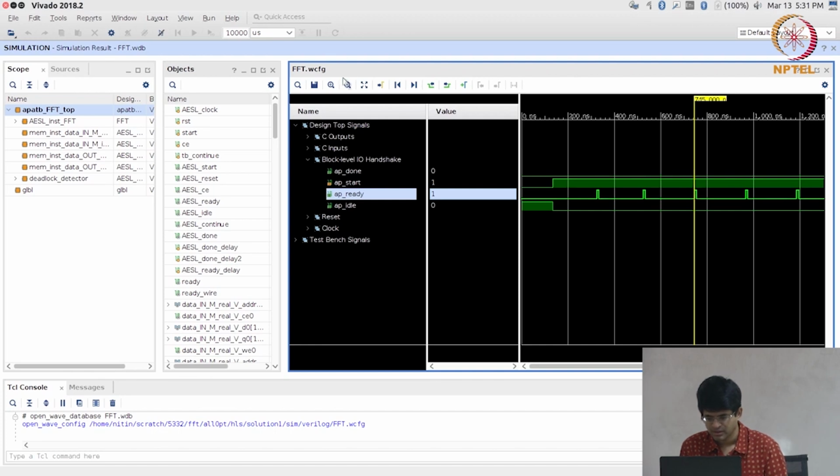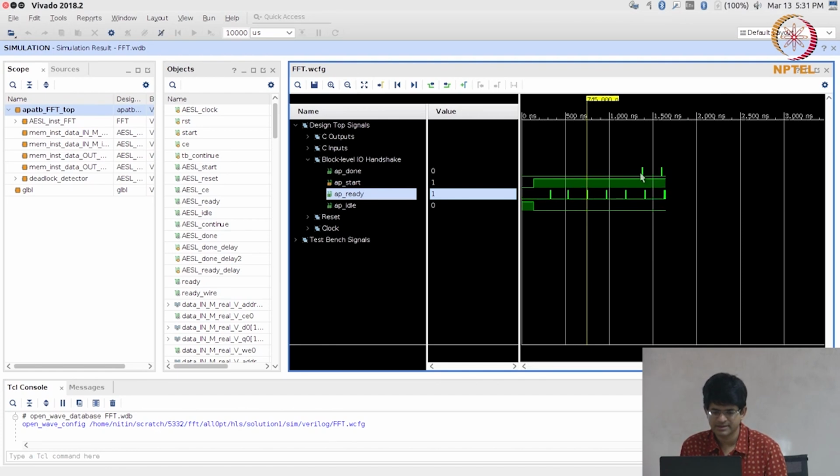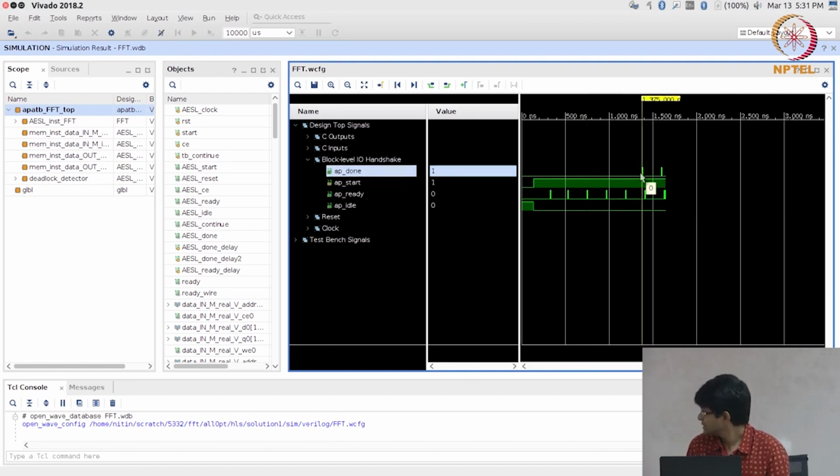Okay. Where is our done signal? Here it is. Okay. So, the difference between the done signal and the start signal corresponds to 124 clock cycles. That is where it got the measured latency from. Okay. And you can see that 20 plus 25 times over here plus something else, this is around 124 clock cycles. Okay. So, the way that the test bench works is, because you had only given it one